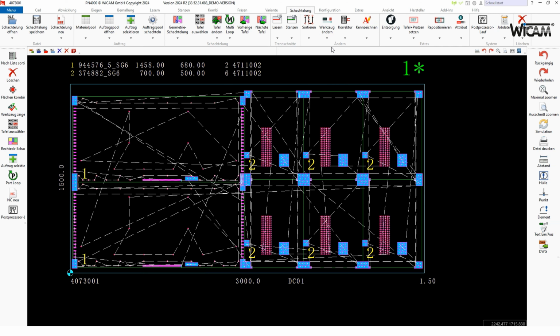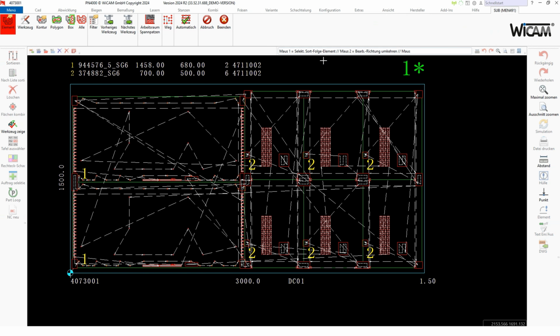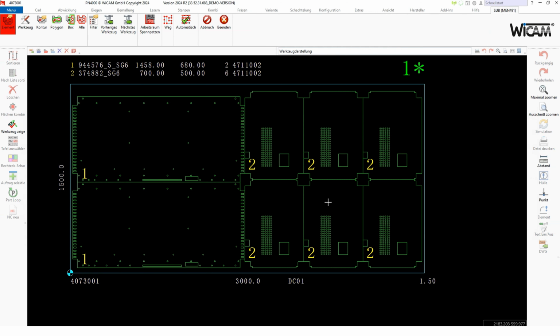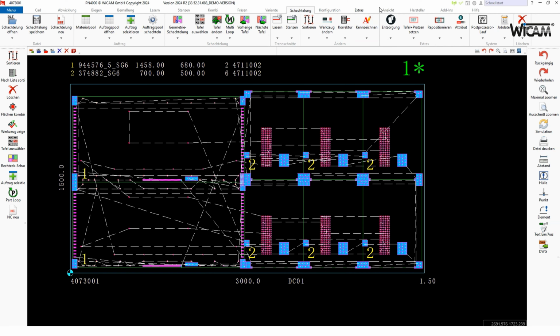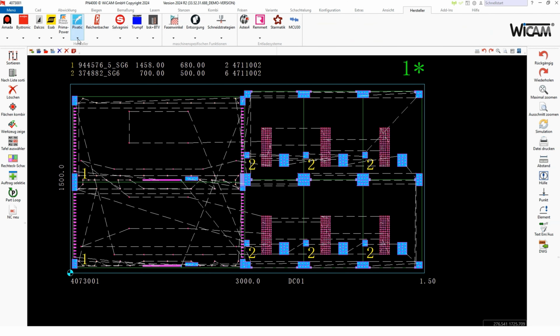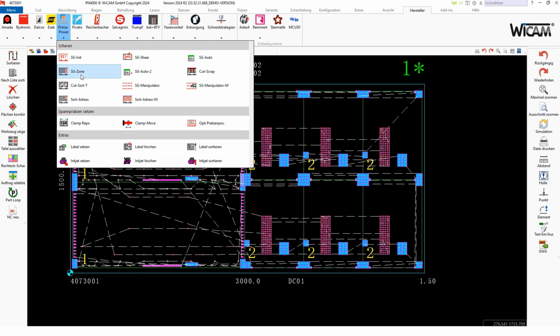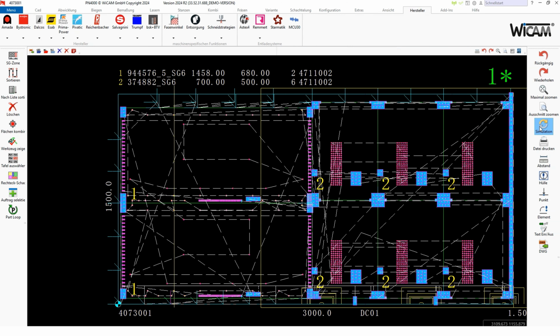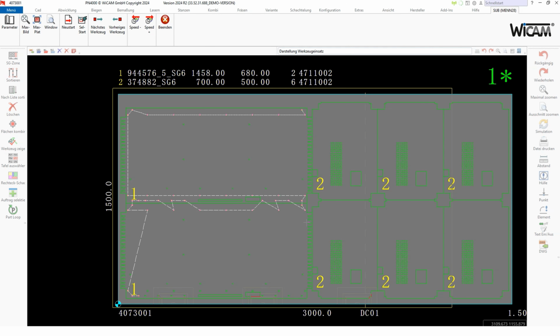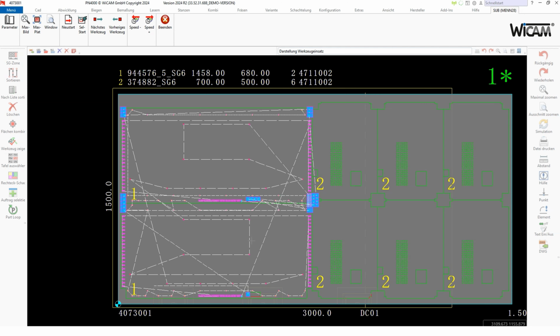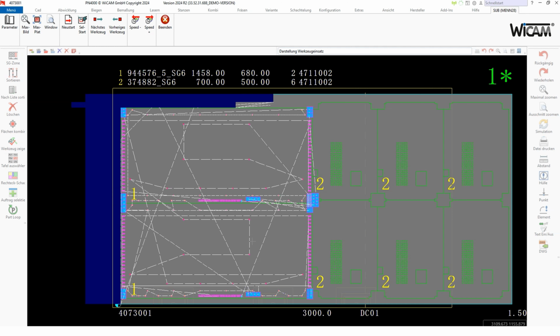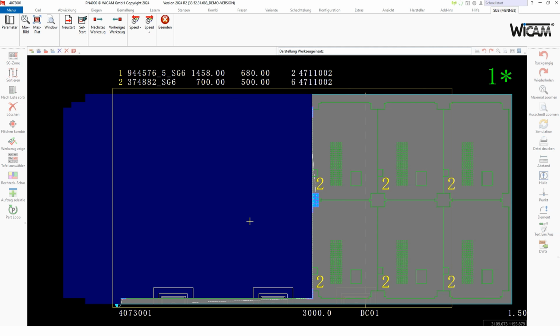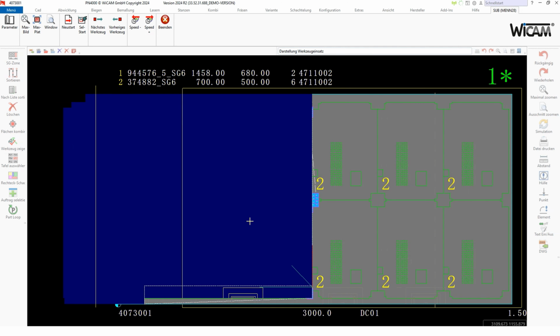The next step is to sort the tools. And we want to optimize the travel path. Then we set the shearing strategy for the Prima Power fully automatically. The program is now optimally prepared for a punching shearing combination. Here you can see the shear cuts.